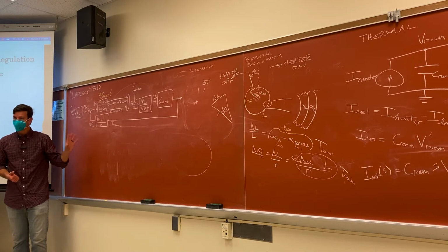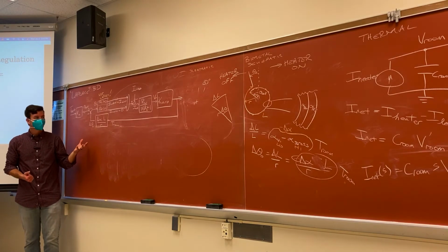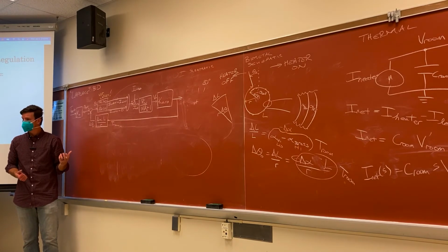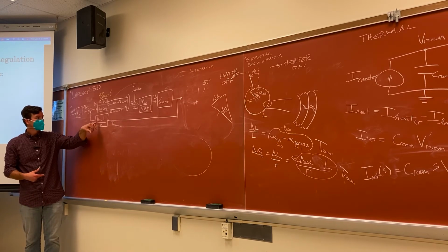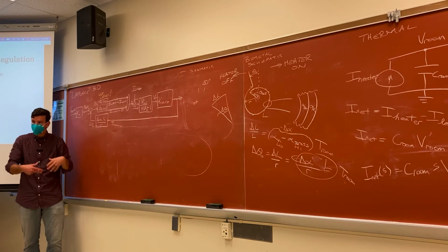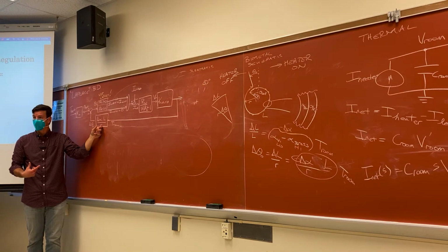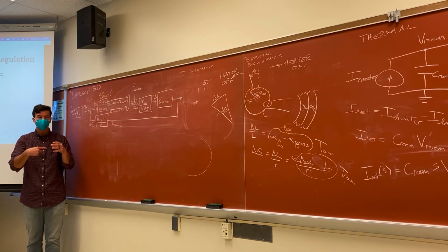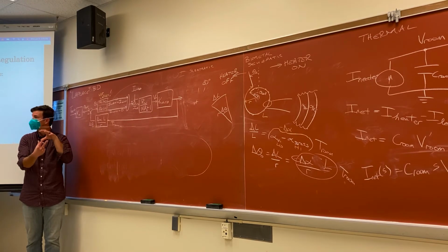Now that we have a mathematical Laplace model of the system, we can go and actually figure out what each of these parameters does. We haven't designed anything yet. Principally, what I would be interested in as a control engineer would be the effects of these three things. But straight away, I can see that delta alpha and L both contribute in the same way, which is the inverse of what the radius does. So if I'm looking to design that coil, I could either make it longer or with a smaller radius, and that would have the same effect.